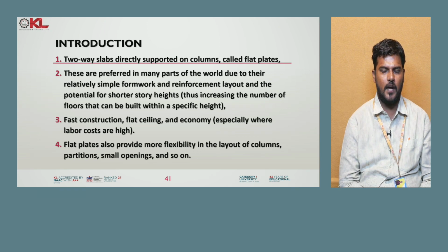Two-way slabs directly supported on columns are called flat plates. These are preferred in many parts of the world due to their relatively simple formwork and reinforcement layout and the potential for shorter story heights. Flat construction, flat ceiling and economy. Flat plates also may provide more flexibility in the layout of the columns, partitions, small openings and so on.